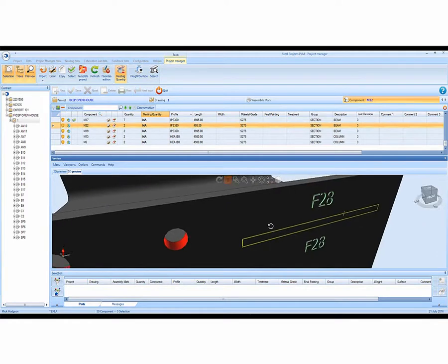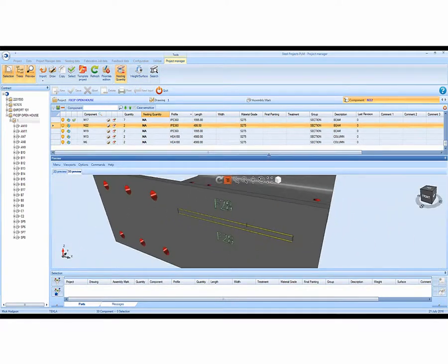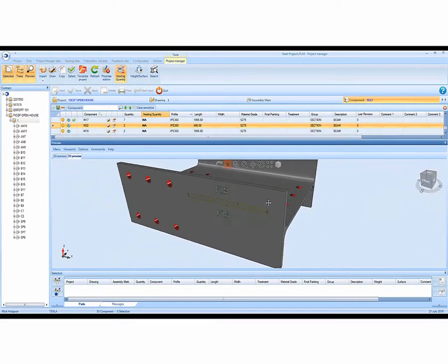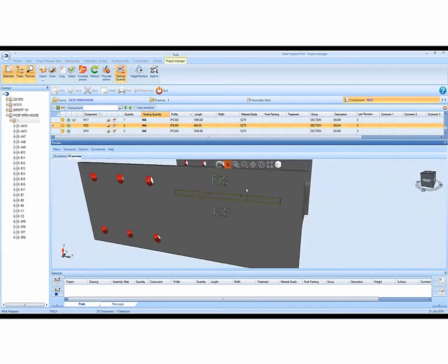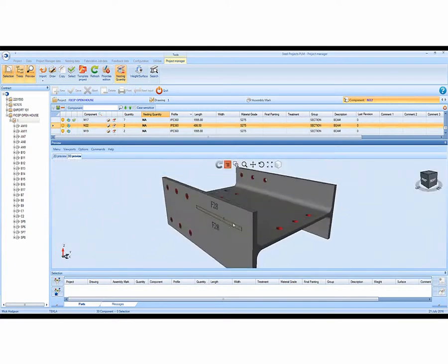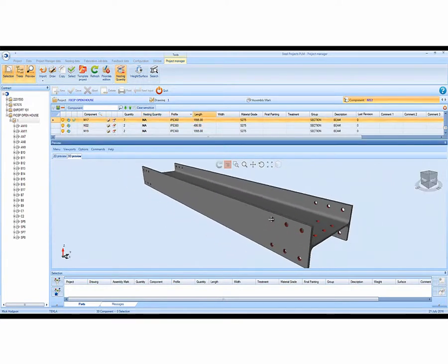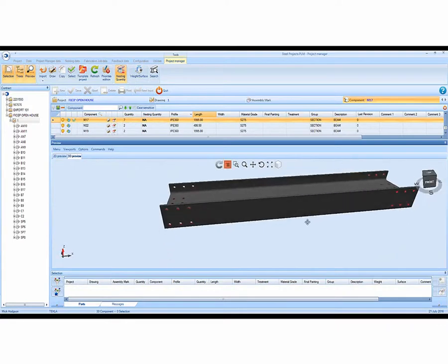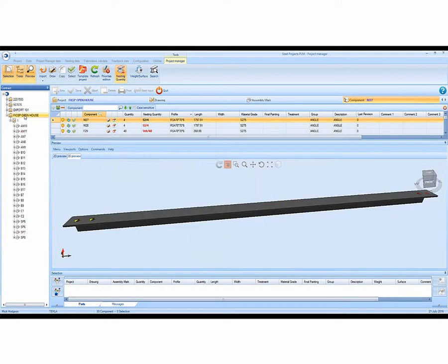If you zoom in, you can see the layout information, the marks of the piece that's connected, so that's the plate that's connected to the beam, and the scribing or layout of how that piece is fit together. So the machine will actually mark and show the fabricator how those pieces go together without any manual layout whatsoever. So, a simple enough process, just a few more examples and a few little walkthroughs.